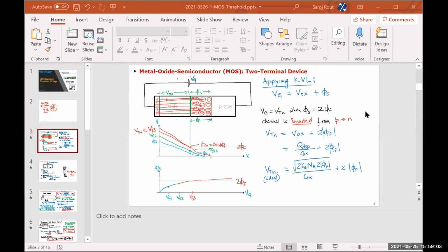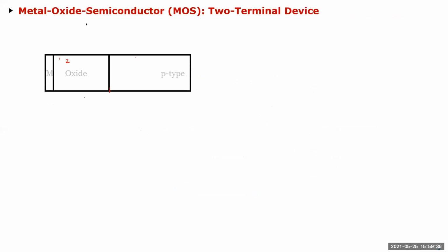Typically, with the signs, if I'm in doubt and I know the direction I have to go, I just take the modulus. You'll see when we do PMOS and NMOS, all the signs are negative. When I started designing, I wanted to avoid all the confusion, and I know which direction the voltage or the current needs to go, so I just take the mod of those values. I'm not sure if the literature uses the modulus, but here it is positive, so it should be the same. For the PMOS derivation, you can take the negative of that, or the modulus, or just take 2 phi f, and that should work as well.